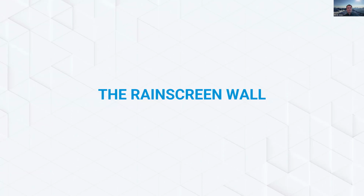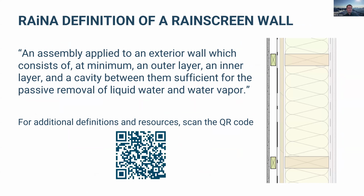Okay, so the definition, which we've come up with a lot of input from industry experts, is as simple as we could make this definition. But it's an assembly applied to an exterior wall, which consists of, at minimum, an outer layer, an inner layer, and a cavity between them sufficient for the passive removal of liquid water and water vapor. Okay, so it's a bit of a mouthful. So we'll break down what that means.